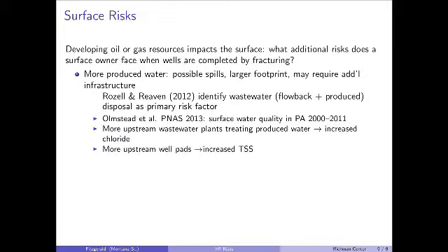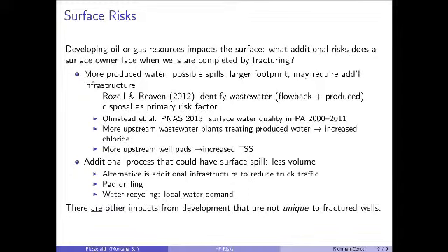The last thing I'll talk about, because Chuck did a great job of talking about what QEP's done with having a network and keeping trucks off the road, having an infrastructure network in place that carries produced water from the wells to a treatment facility, and that may be used for recycling. Okay, that really requires the pad drilling model to have the density. For example, in the Bakken right now, we're using 2 section spacing units, 1,280 acre spacing units. Most of those are held by one well. It's just not worth it to run pipeline out to each one of those wells. When you've got 50 wells on one pad, then it becomes much more economic.